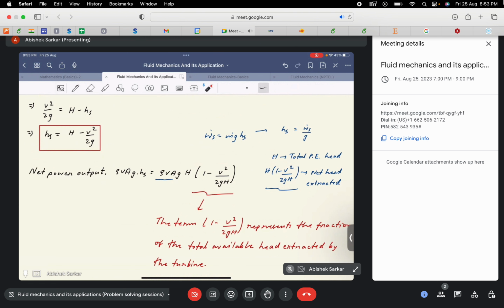Also there will be certain other modifications that we need to check, the various viscous losses and mechanical losses in the case of turbines. There will be various mechanical losses in the shaft while it rotates, so these are things that we need to consider. Again, if we couple this shaft with a generator, the generator would have certain losses, right?